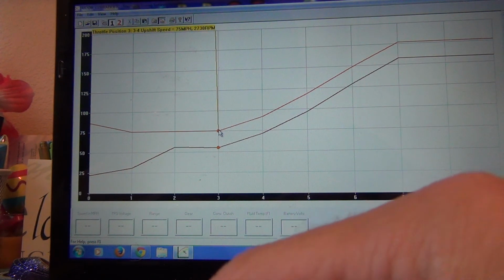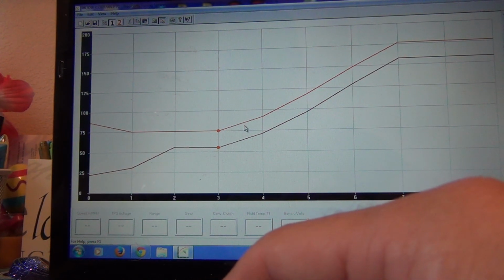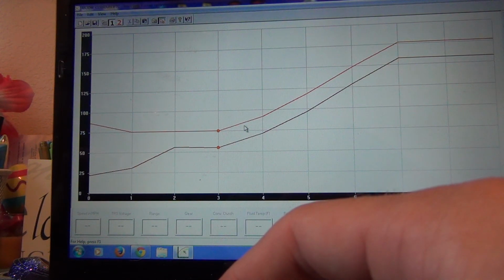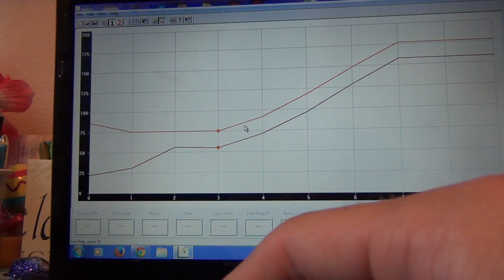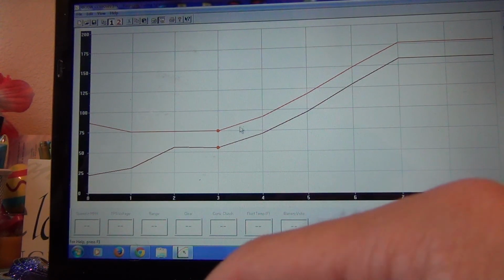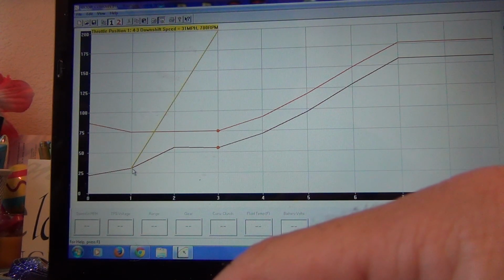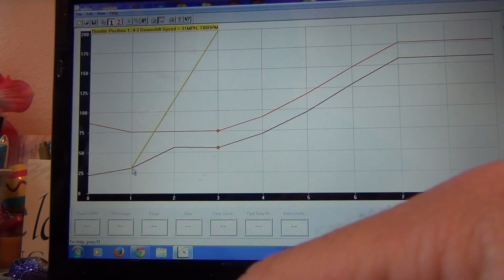The problem that I was having, like I said, was the overdrive was kicking in fine, but coming out of overdrive, the road leading to my house is 55 miles per hour. Well, let's say you're doing 70 miles per hour, your overdrive kicks in. You get stuck behind someone that's slow, you can't pass them, you're at 55 miles per hour, now you're bogging down, like this. For whatever reason, my overdrive isn't going to kick out till 31 miles per hour.